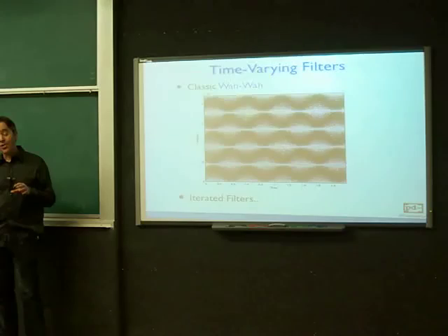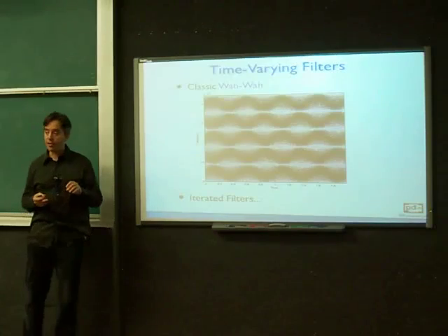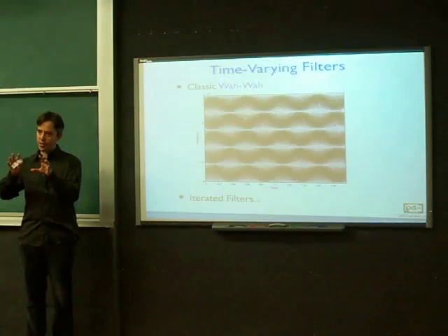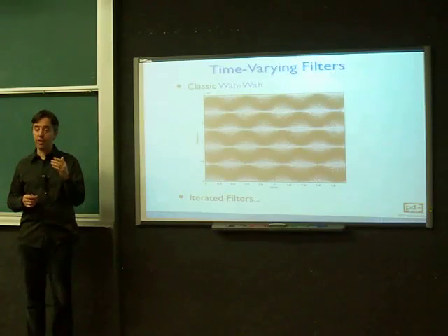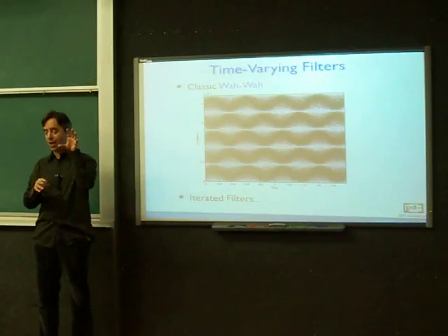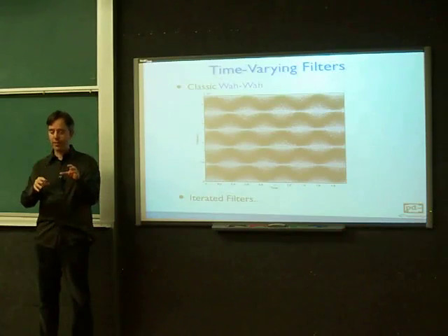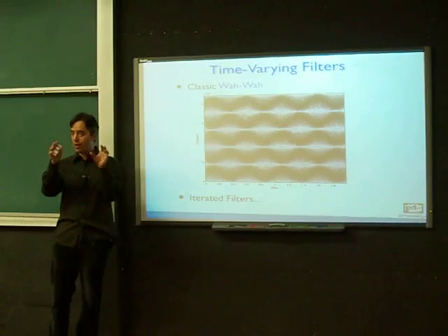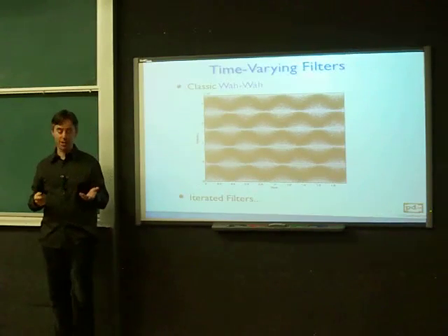That's for just stationary EQ. The idea of that is that you've got the mixing desk, you've got some sources coming in. You want to have a fixed adjustment of the energy in different frequency bands, because there might be some particular source that has a particular peak and is either dominating the mix or it's not clear enough in the mix. And you can just move this with a parametric filter.